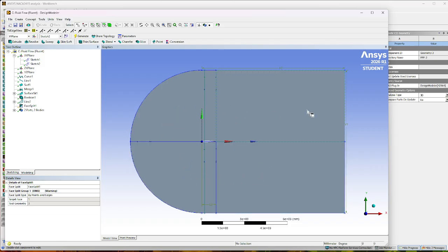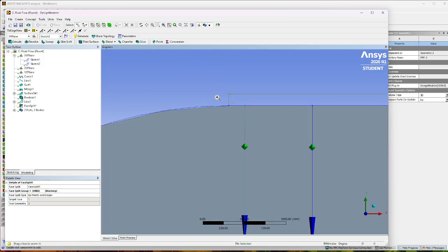which is really cool. So now we're gonna do a couple more things. Before we move on, if you zoom in here and you do the edge select, these are 2 different edges. And when you do the meshing, you need to merge these, or else ANSYS will again scream at you, and that's not pleasant.